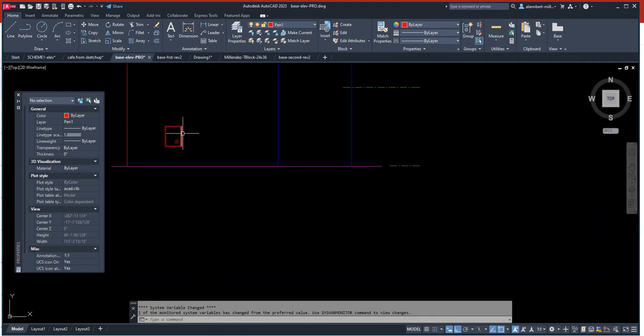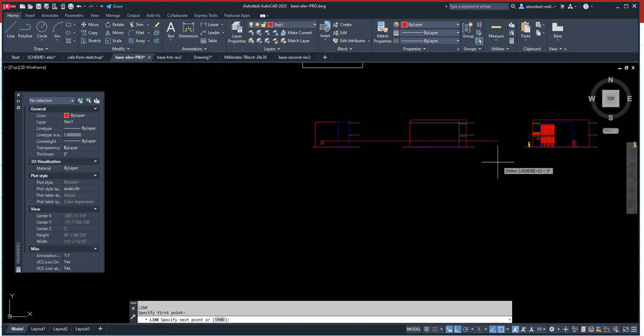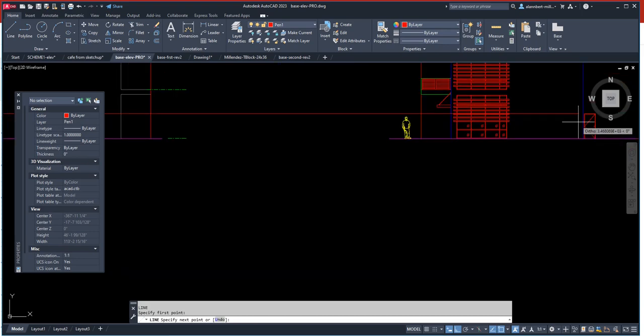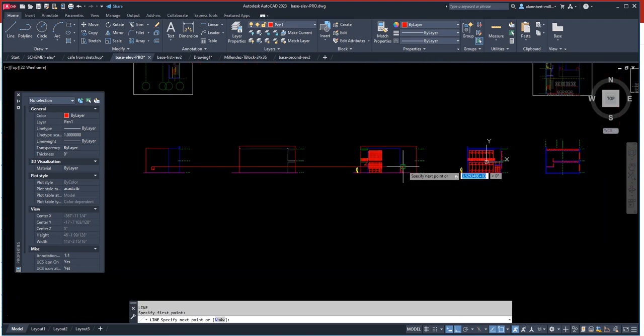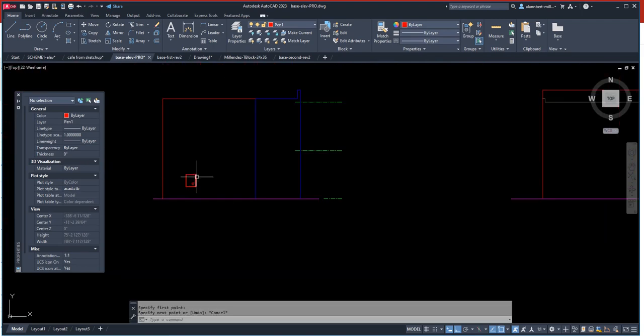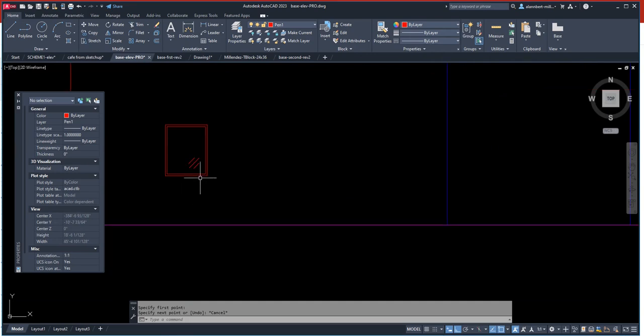When you're creating windows, and that's the reason why I put it in, it is typically at the same elevation or level as the door. So you can see here, okay, they're at the same elevation as the door. Okay. If this was an operable window and it can be used as a means of egress or exit, then the minimum height from the floor to this window would be around 36 to about 42 inches.